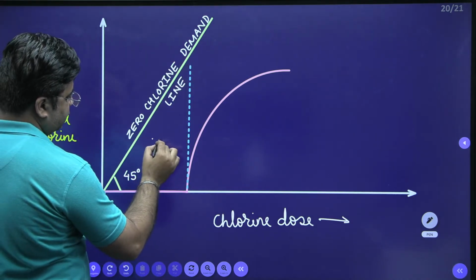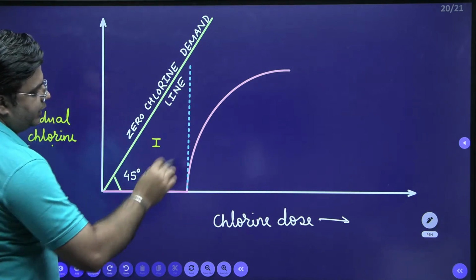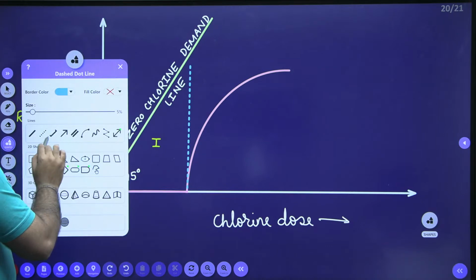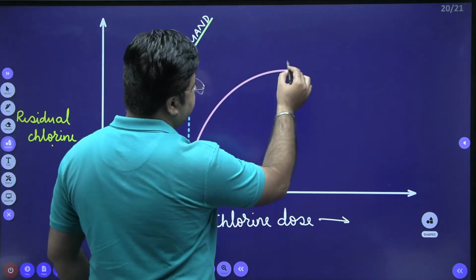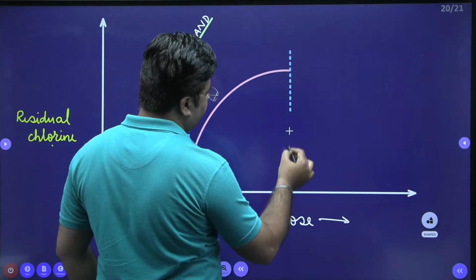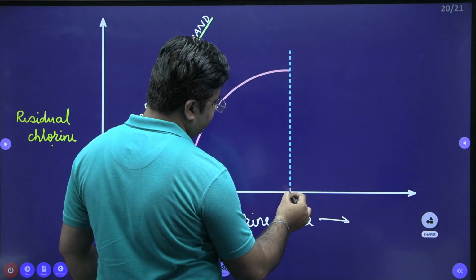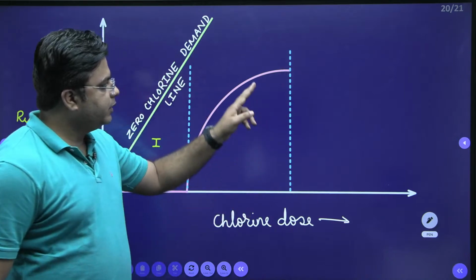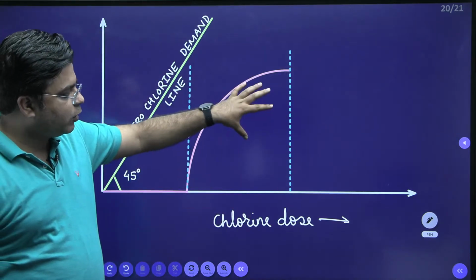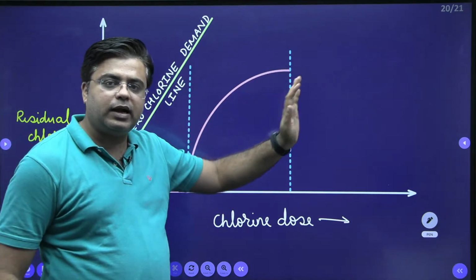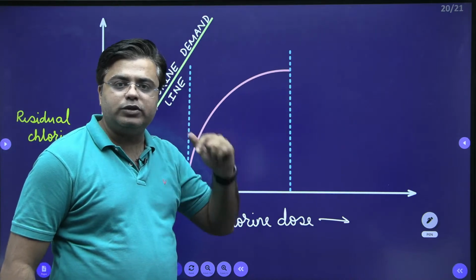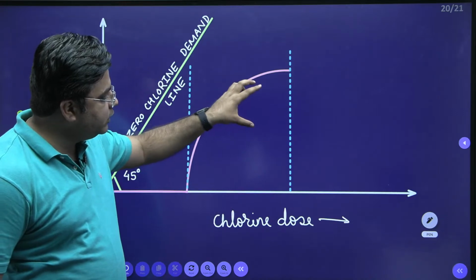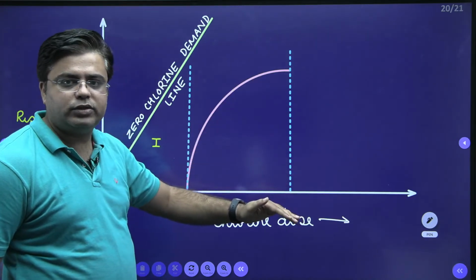This is phase 1, right? Then you have the second phase of your curve where chloramines are getting formed and you are seeing more quantity of residual chlorine that is getting formed, right? Now, beyond this point, these chloramines that are formed in the system start carrying out the decomposition of the organic matter, and the quantity of these chloramines keeps on reducing.